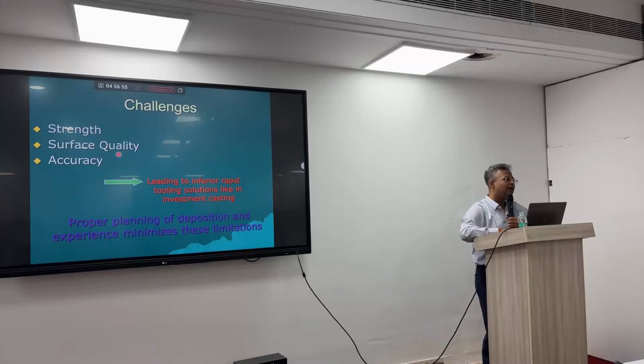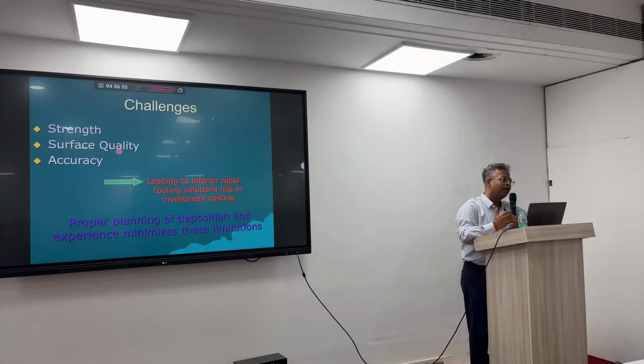The surface quality is definitely inferior because you are depositing the material layer by layer. It's not like continuous manufacturing. So the surface quality is definitely going to be poor. You need to do some chemical treatment if you want to improve the surface quality.